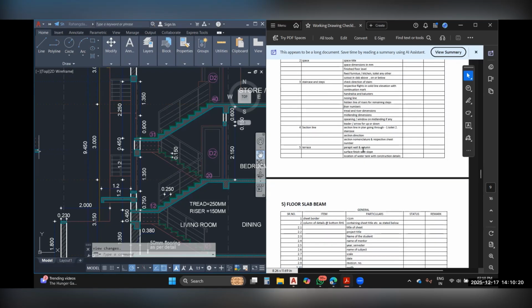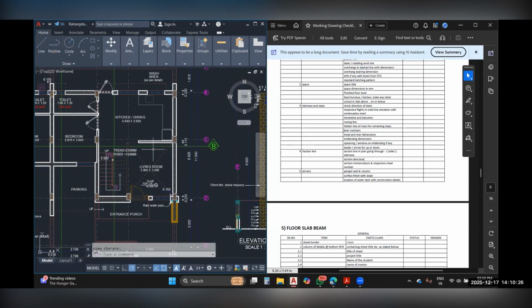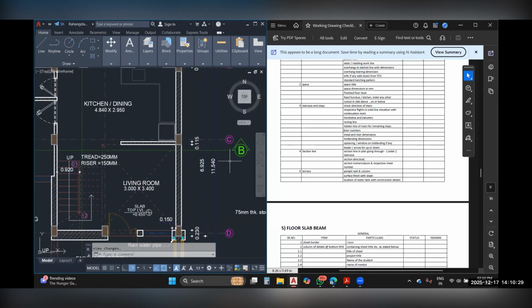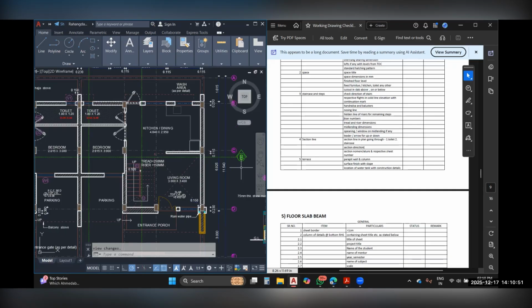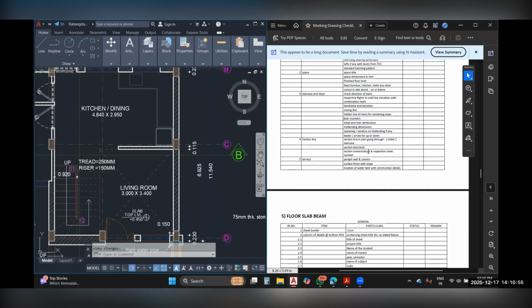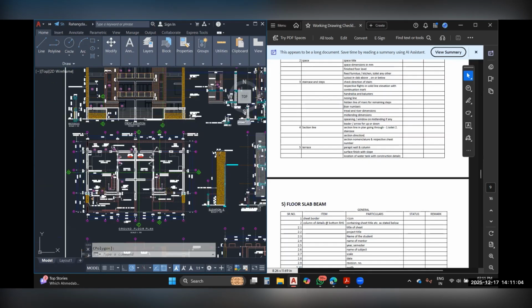Next is the direction of the section. So just mentioning the section line is not enough. You need to also show the direction into which one has to read or coordinate the section with the plan. Also, the nomenclature is required. Just showing the line and the arrow is also not the case. You need to also put up the nomenclature for the sectional line. Then, so that's it for the plan.